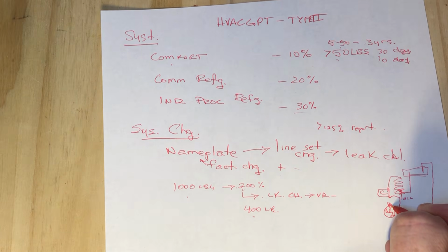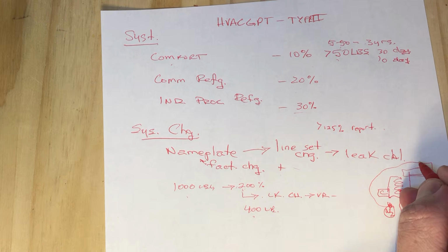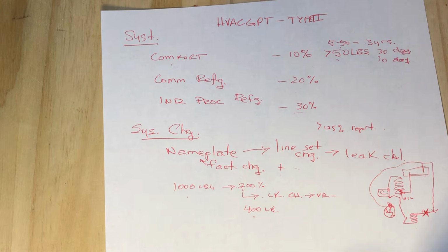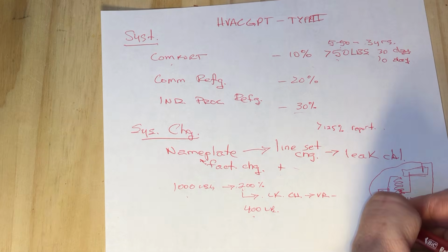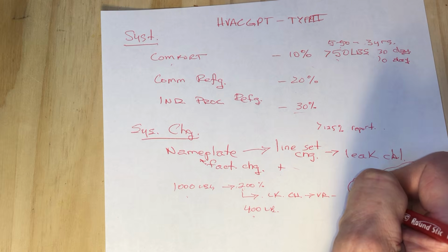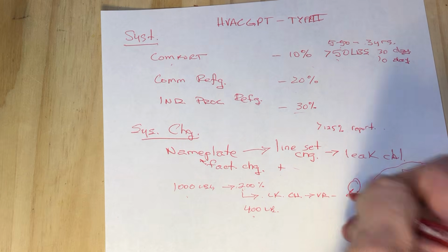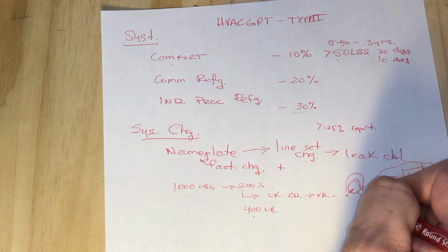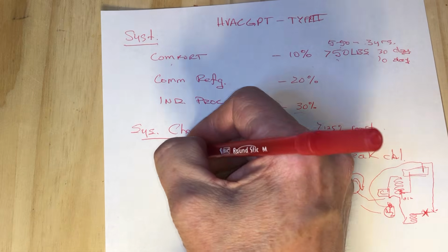So you connect that up to your valve here, and then blow it through while you're doing your braze. And then let's say we want to verify that you got a leak. So you've got your low pressure gauge hooked up here, and the low pressure gauge is at 0, and then you're going to pressurize it to the test pressure of whatever the nameplate said.